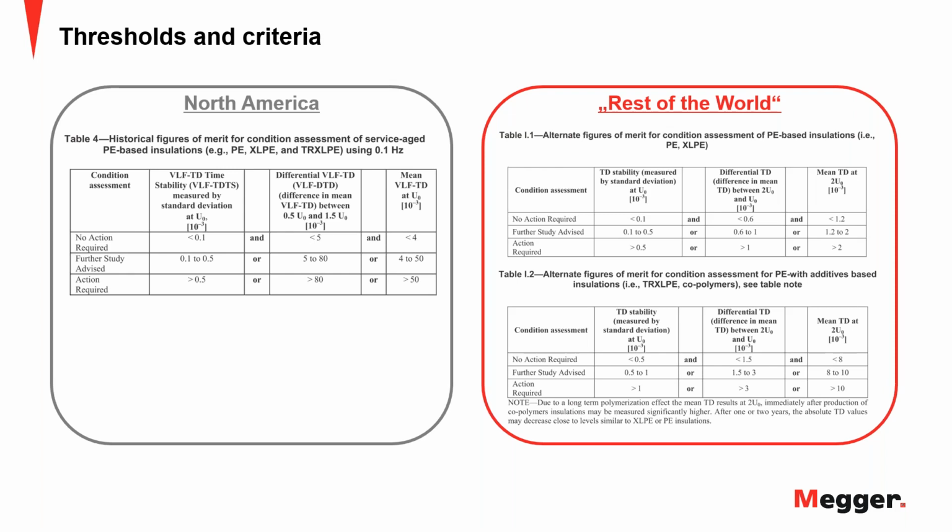Maybe just to add a little bit to it, when you compare numbers, you have to distinguish what type of cable you have. You have a solid dielectric cable, or you have a paper oil insulated cable. Or you have solid dielectric accessories, basically resin type accessories, or heat shrink, cold shrink, or whatever, and you have liquid-filled accessories, right?